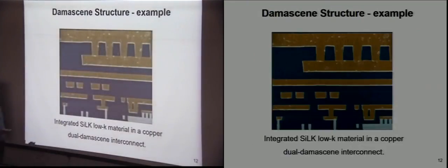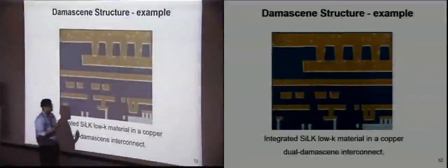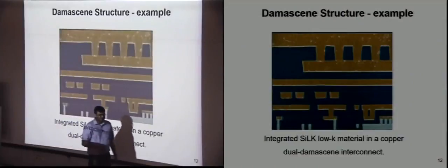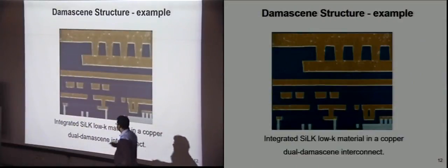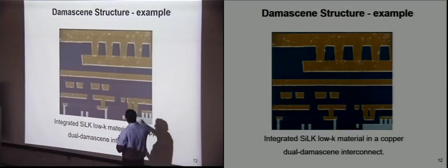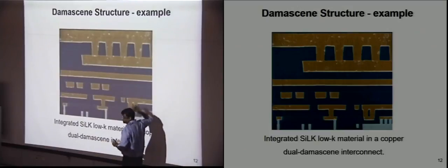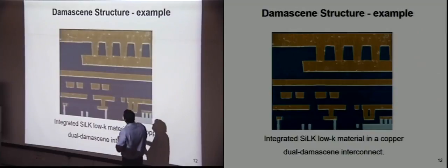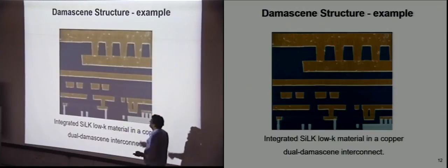Okay, so this is an example of multi-layers of copper being formed. Down here is all your transistors and things like that. Since it's a cross section, you cannot really see all the intricacies of it because there are multiple transistors within the plane of the screen. So these are all the different connections, dual Damascene processes, etc. utilized.